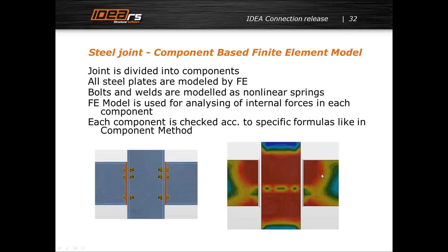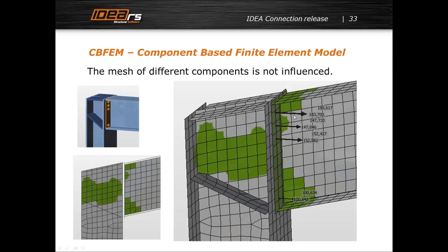So we calculate stresses and internal forces in this finite element model, and then we apply the same checks as in the component method, the same checks which are in Eurocode. So it is not replacing the component method, but it is a synergy of component method and finite element method.